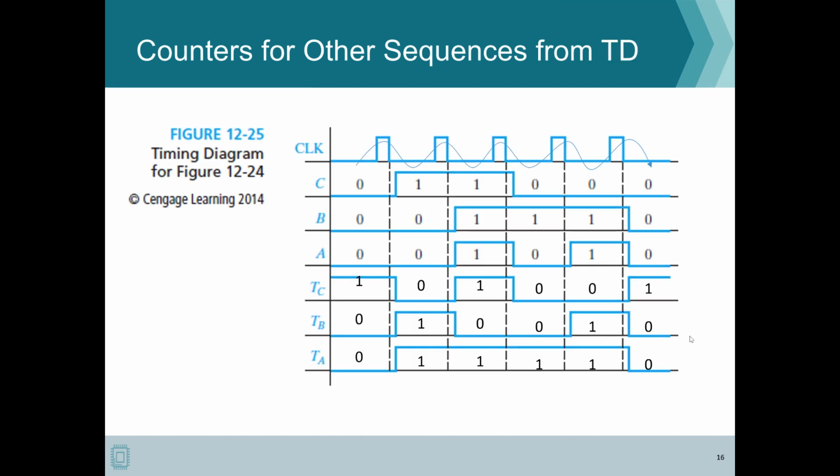So in some cases, instead of actually giving you the state transition graph, you could also be given the timing diagram. So once you're given the timing diagram, you can see that here, this is where the dotted line says that that's when the transition on the flip-flop happens. So you're given the values of C, and so what actually happens is, for this instance, if this is your current state, then this will be your next state.